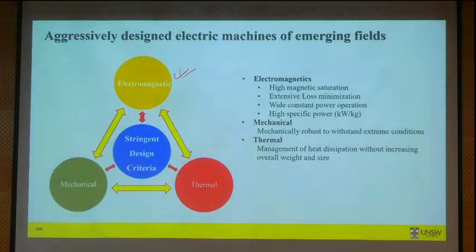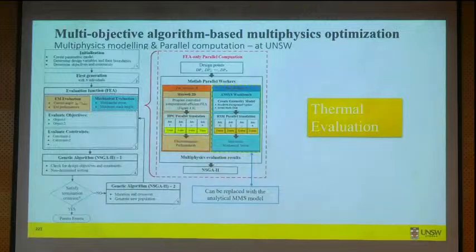Okay, so that was the case for us when we did this high-speed IPM motor that we have designed. So high-speed IPM design, we are pushing the envelope, right? We are operating at the boundary of the mechanical stress actually of IPM machine. So the mechanical stress must be part of the optimization. And so that's why we had our genetic algorithm-based electromagnetics optimization, but then we added the mechanical stress analysis as part of it. Okay.